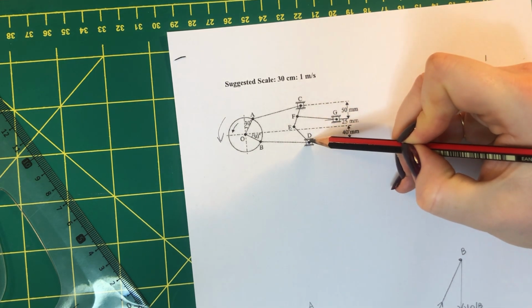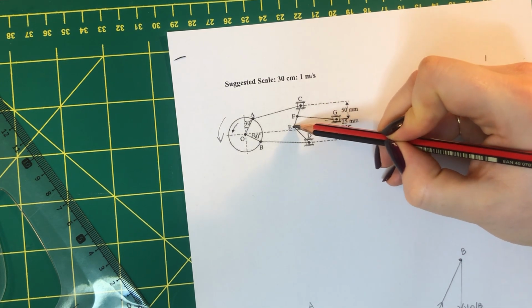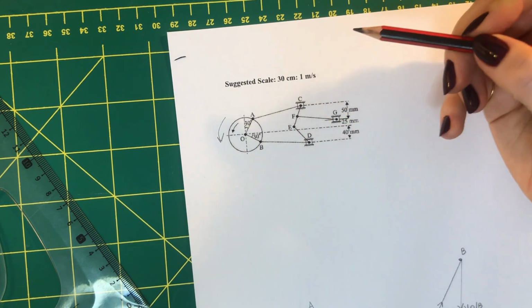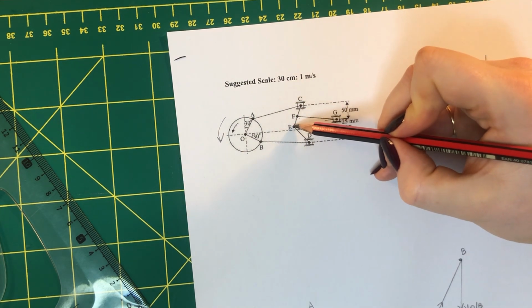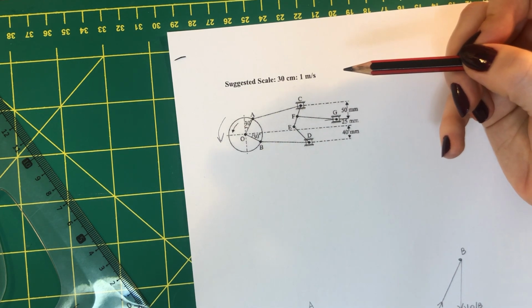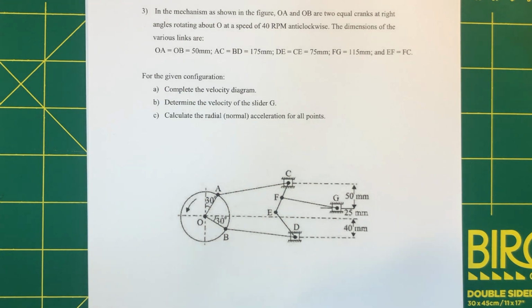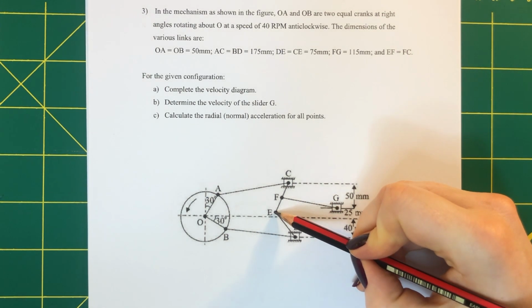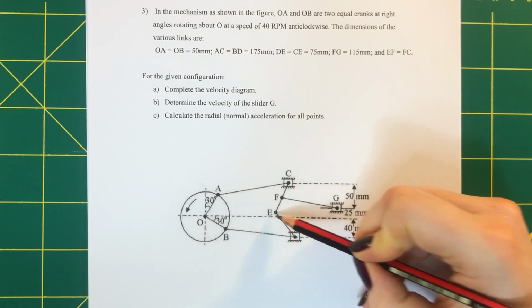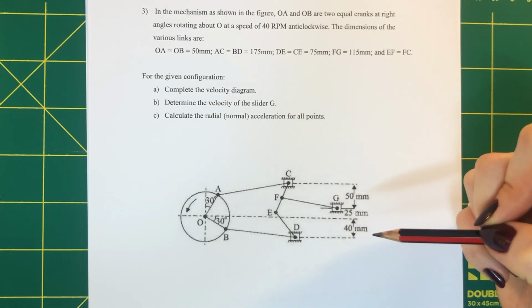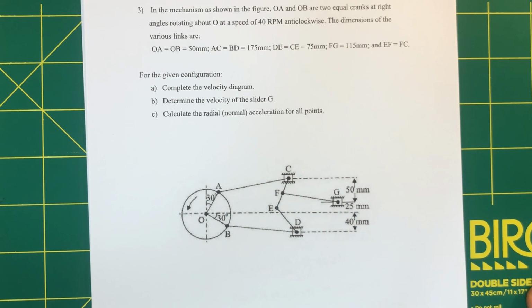So I've got C and D. On this link I have E, F and C. So my next point is going to be point E, and then from there I can use a ratio to find where point F is. So now it's time to find point E. This is at the center of the links connected to C and D. So I'm going to write 2 more relative equations.